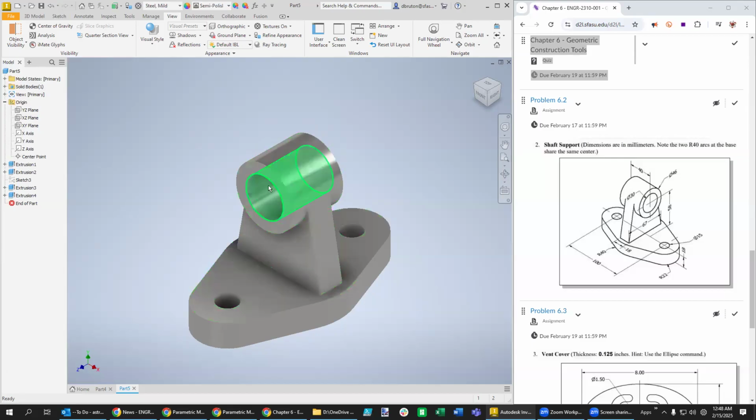And you might even convince them that it's going to need some fillets here on the edge, so it's going to be less likely to cut into anything, whether it be a person, making it uncomfortable for a person to hold, or maybe even the ability to get that tube in here might need a chamfer on that surface. So making a part that your client can visualize is going to be helpful in industry.